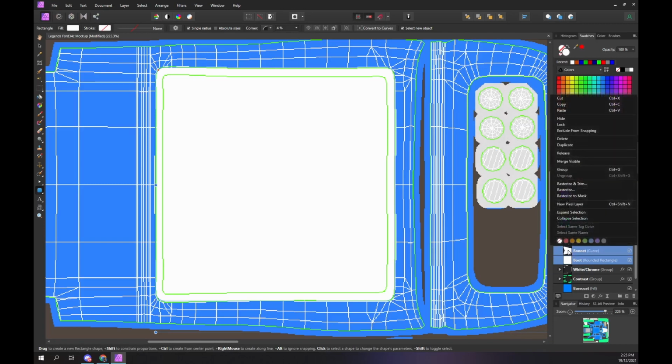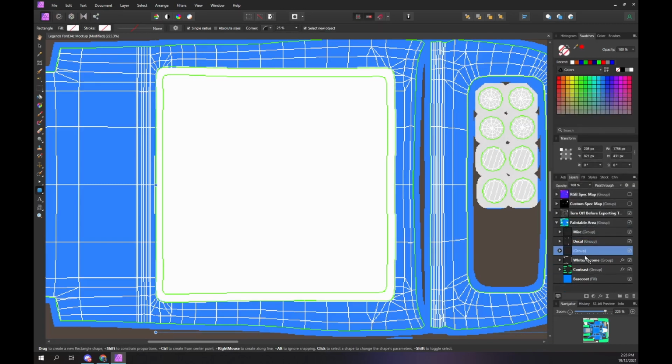Now we have two layers that identify parts that are to have a carbon texture. That is their only purpose, they will not be used to paint the car. Put them into a group named parts to make it easy to use all these carbon parts in one step. We can add, edit or remove parts inside this group at a later date. Create a group named carbon containing the parts group.